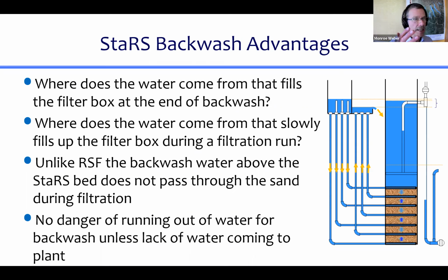Does that water is slightly dirtier because it includes water that went through the filter during backwash. So does that water ever go through the filter? It's interesting. And Ravi's got it. The answer is no, it never goes through the filter, because the next thing that's going to happen is you're going to switch over to backwash mode. And when you switch over to backwash mode, you flush all of that water through this siphon pipe, and it goes to waste or to your backwash recycle tank.